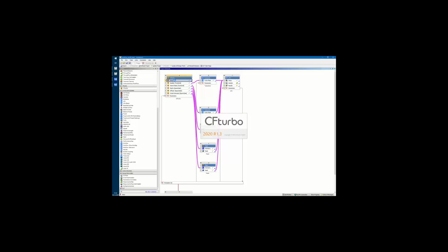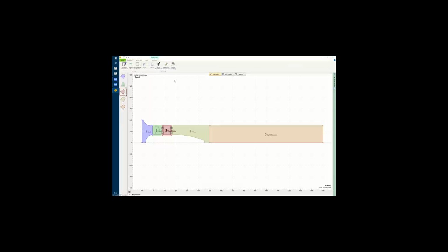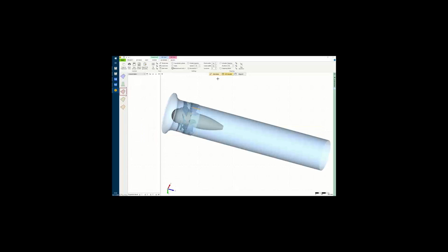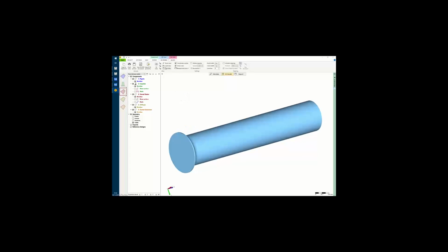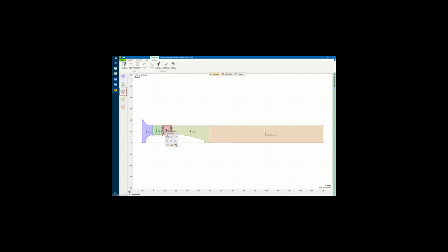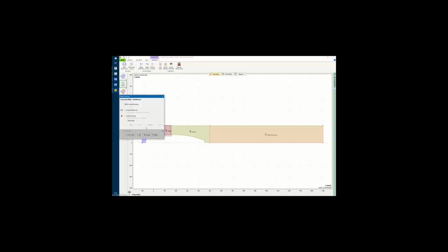And I can quickly show it to you. I'm going to switch to the 3D model. And instead of recent state, I'm going to select fluid domain solids. And maybe I need to run the model finishing. So I need to activate the solid trimming because it wasn't activated, because we don't need it for TurboGrid exports. But that's no problem. It just takes a couple of seconds.